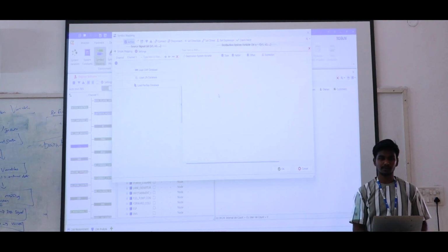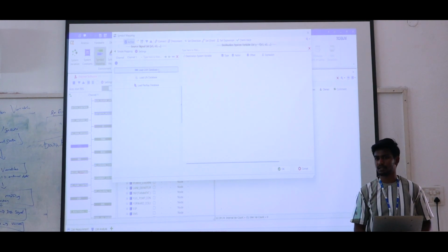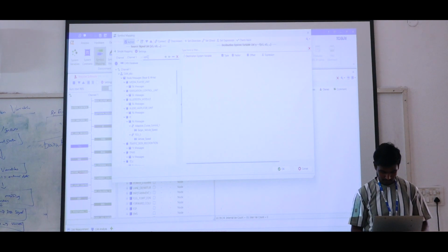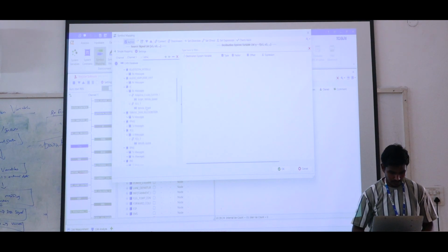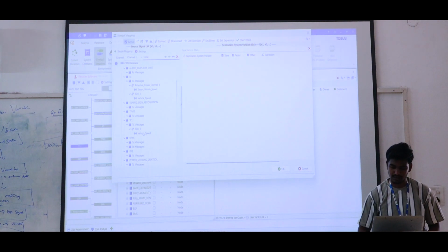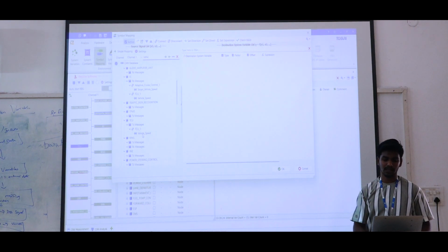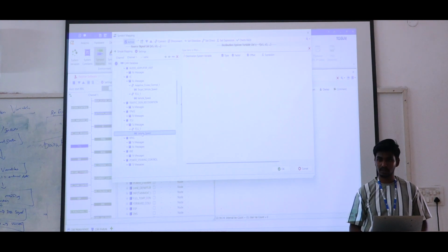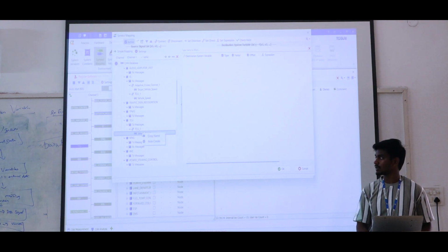So same concept. Go to load CAN database. Okay. And then check vehicle speed. So showing some nodes, particularly like a TC node, which means we are going to take the transmitter values only. So transmitter node transmitting message TC1. So you have to select the signal and then click.